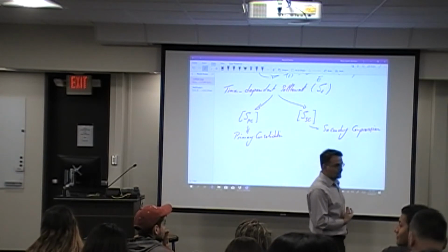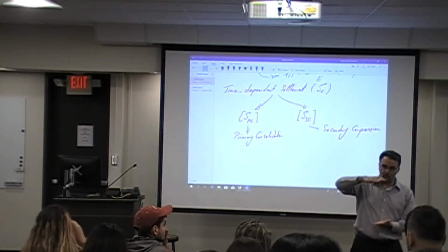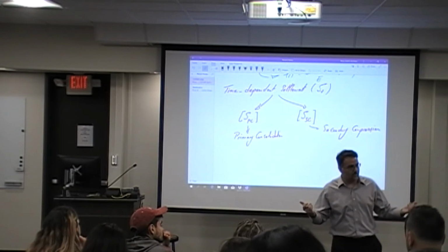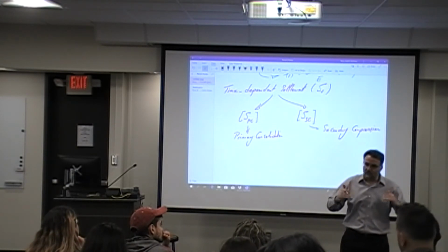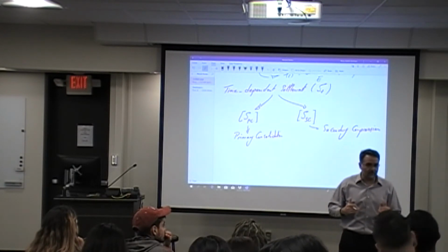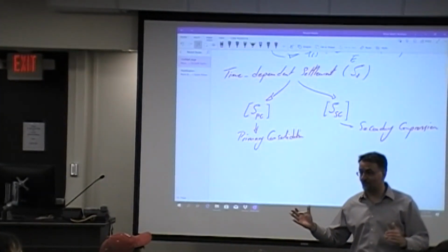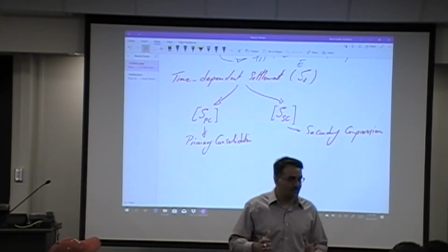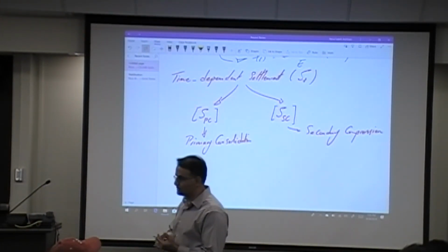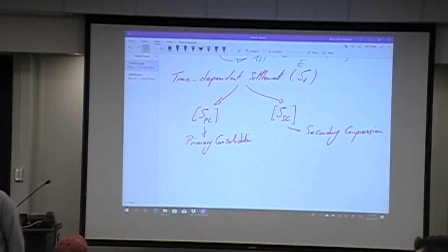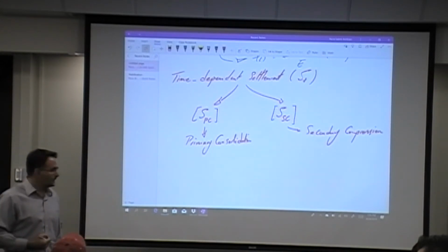So that was what we talked about in terms of the transference of the stresses. So this is exactly the mechanism here. You apply the load from the top, and then you see the water essentially travels outside of the medium. What happens? You see settlement will take place. How fast the settlement takes place depends on the permeability of your soil, right? That makes sense? That's basically what it means, the correlation between the permeability and time-dependent components of the settlement that we have here. So we have two segments here.